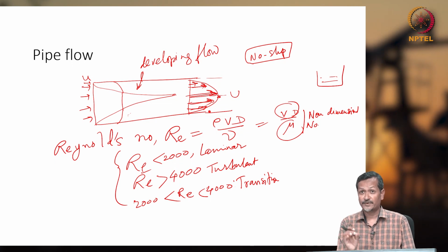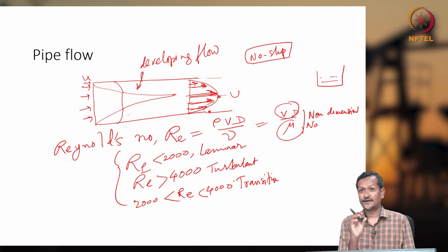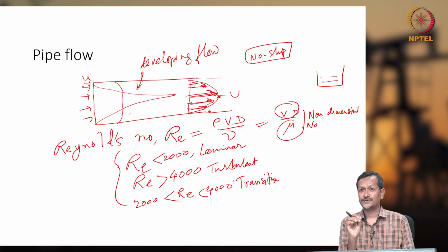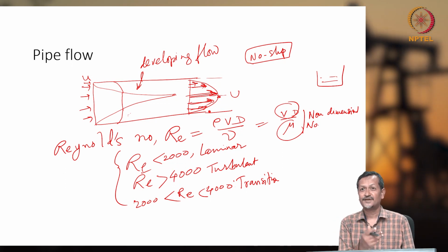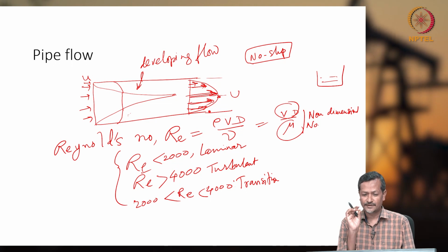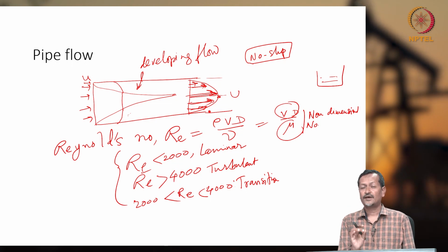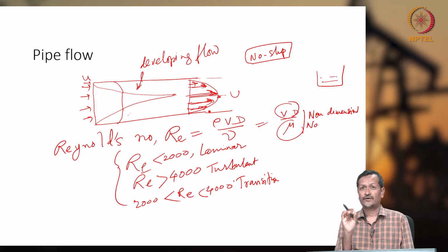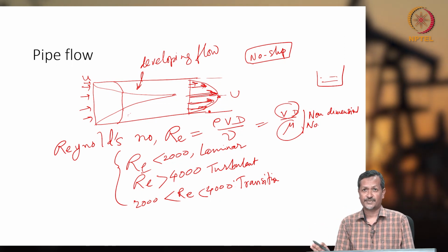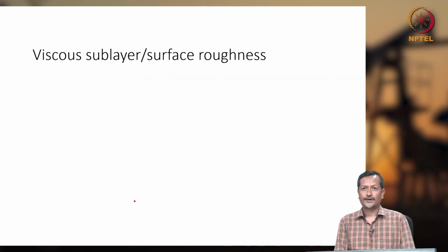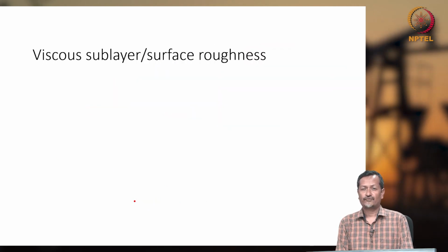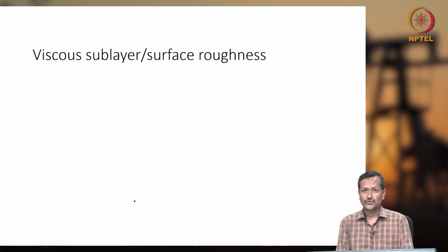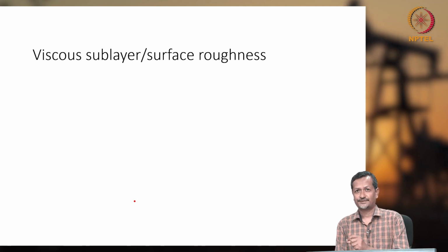It is a non-dimensional number. If I give units in different units, that will create a dimensional Reynolds number, which will be wrong. So whenever you are calculating, you have to check the units are okay, or after calculating you have to check with the Buckingham-Pi theorem whether you are getting a non-dimensional Reynolds number. Okay, whenever you are talking about fluid flow, pipe flow, we talk about friction.